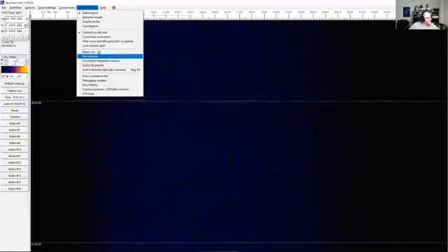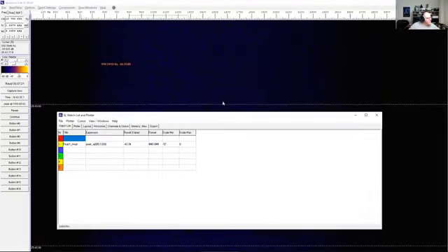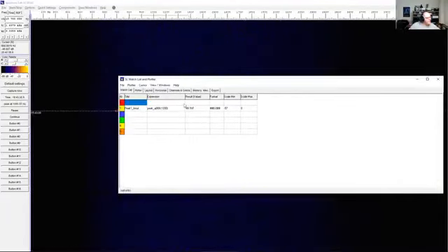Watch list. Okay. Now, if you can see this number here, this minus 42, 43. This is sampling between these frequencies, 800 hertz and 1200 hertz. So the software is scanning and listening for signals in that range. And this is the kind of noise level that's coming out.